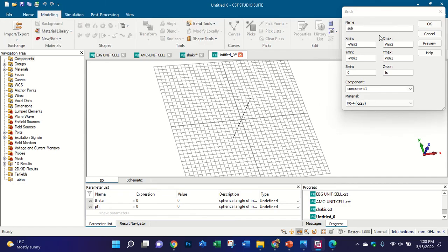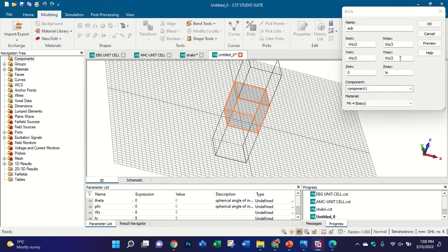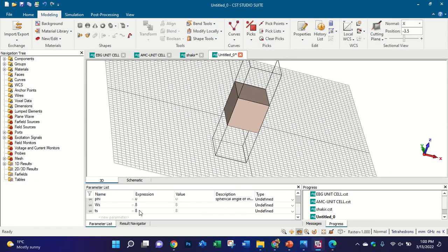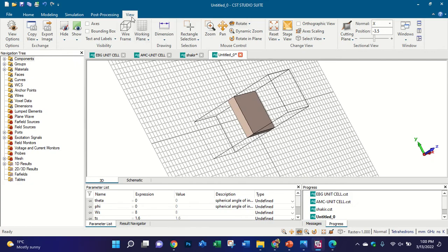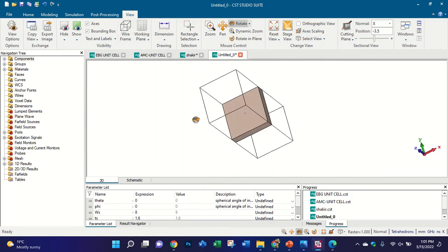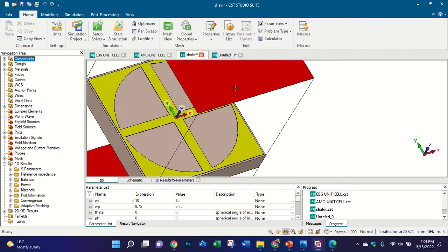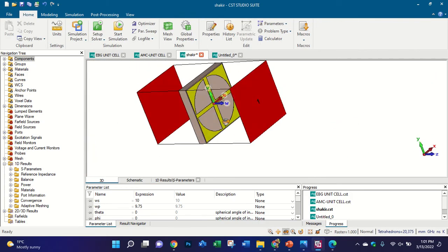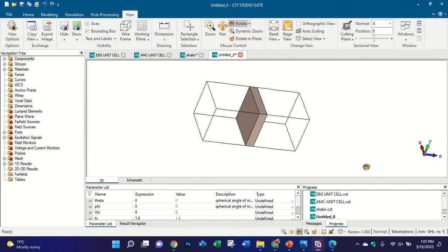Okay, so you have a substrate here. I use FR4 for the substrate. Sorry, I use the thickness of the substrate, not 8, 1.6. So this is my substrate, and in this case this is the same as this one. You have two ports in front of each other, on the back side and on the front. So in that case you can say this is your unit cell.